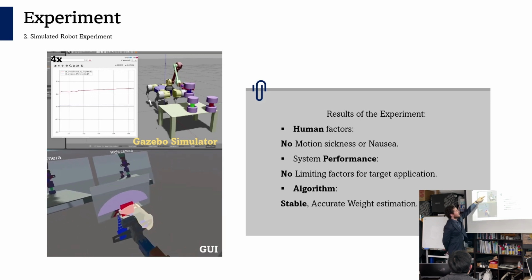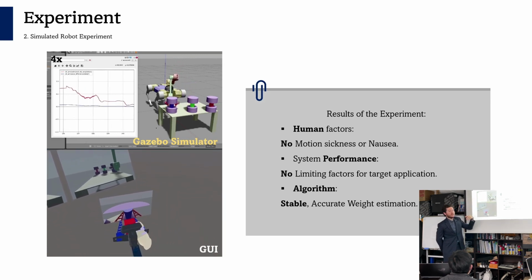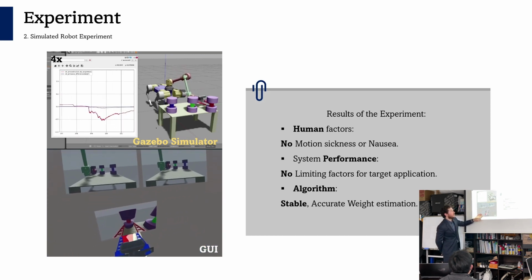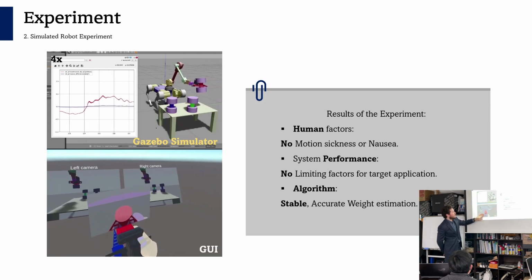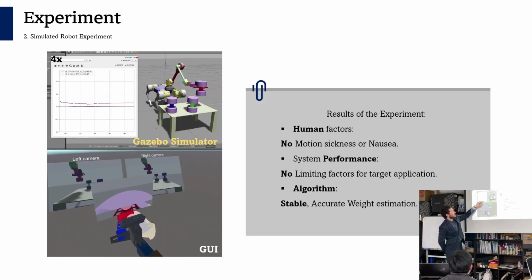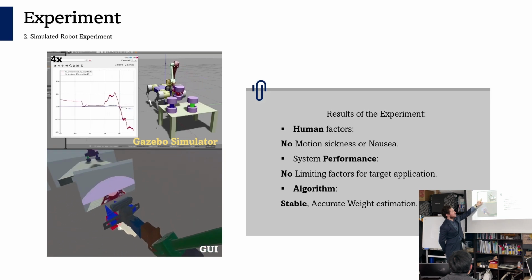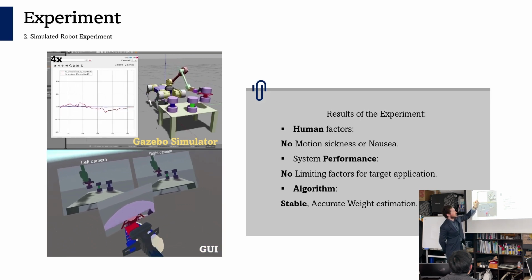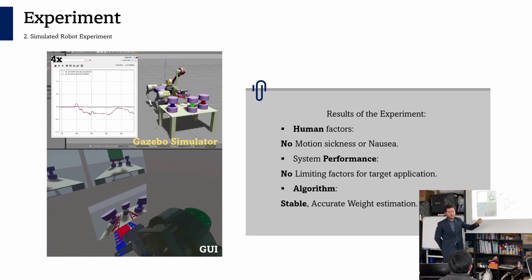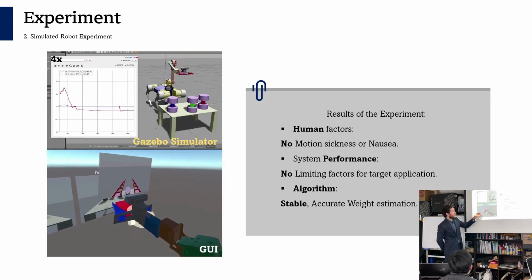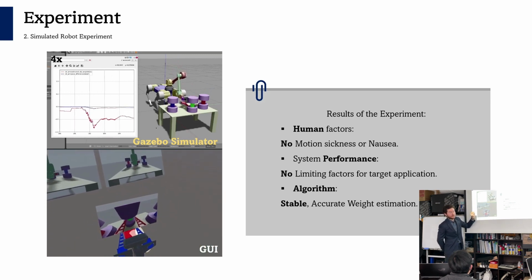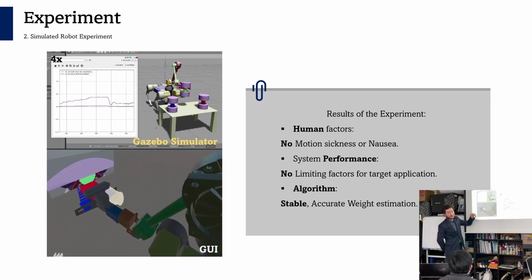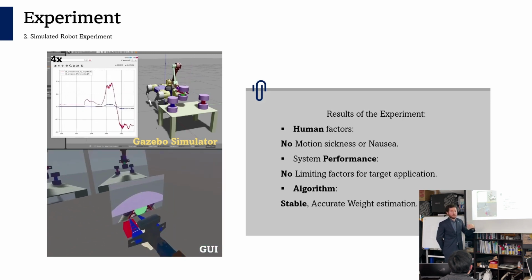It's pretty accurate. Now it means whenever I press a button, it's going to compensate. In the rest of the video, now I'm going to compensate it. Holding this object, now there is a difference. And when I press a button, it's going to be reduced eventually. You can see from here. Got it. Now when it's stable and the reference pose is not moving, there is no difference in the Z direction. But when I put down the object, now there is a minus error because the model is updated accordingly with the added weight.